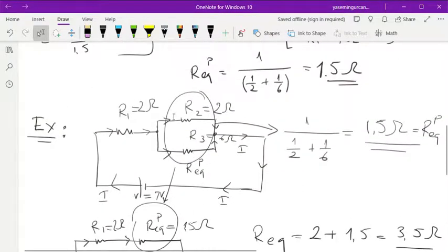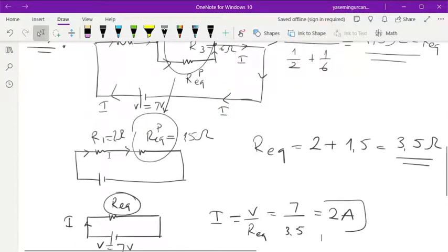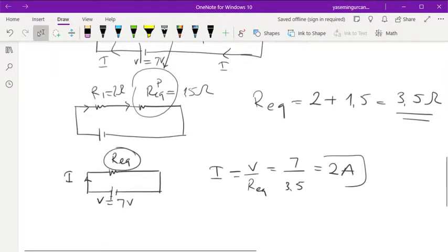Whenever you see a parallel connection in part of a circuit that is bigger than just those 2 parallel connected resistors, get rid of that parallel part by finding their R equivalent value, then replacing it and redrawing the circuit in a simpler manner. See, this is much simpler than what this one looks like. Then, whichever resistances are in series to that value you find, add them and get rid of that part also, and just write them down as a simpler circuit like this.